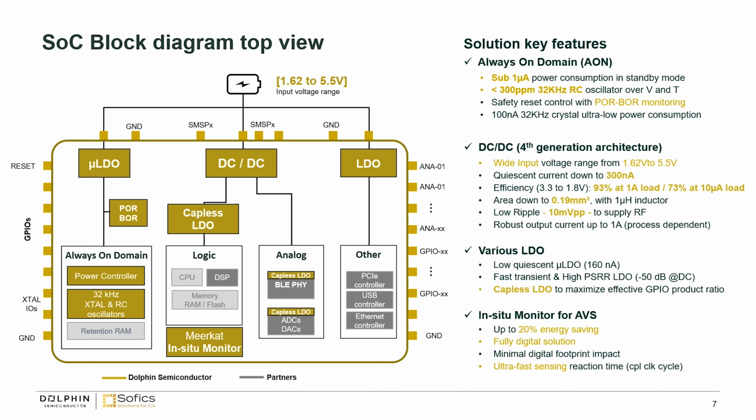Okay, so let's go a bit deeper here. This is a typical block diagram of a microcontroller. Could be any of the well-known microcontrollers, a 32-bit one, for instance. So any product is fitted into a package, right, with a lot of pins, and what matters is the efficient pin count. So what I mean here is in a package you may have pins that are for the power supply, like VDD, pins related to the clocks, and usually with those pins you cannot use them as traditional GPIOs or analog pins, for instance.